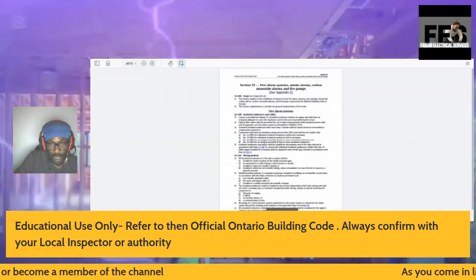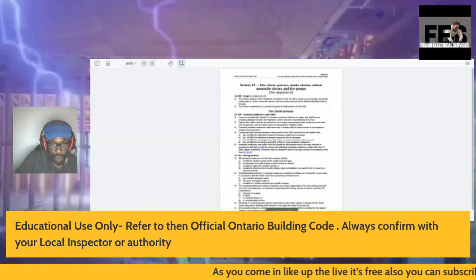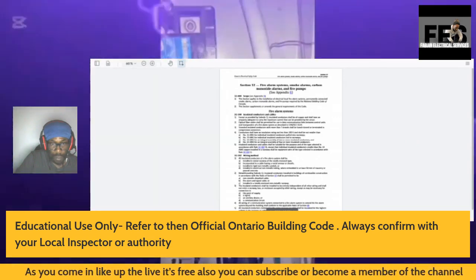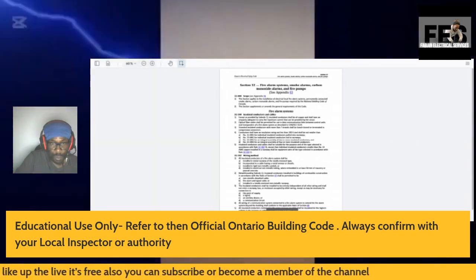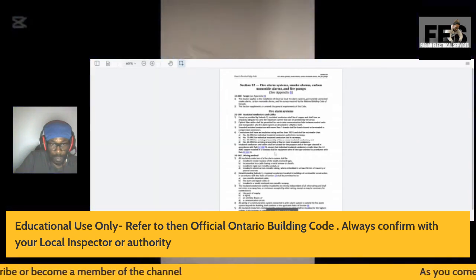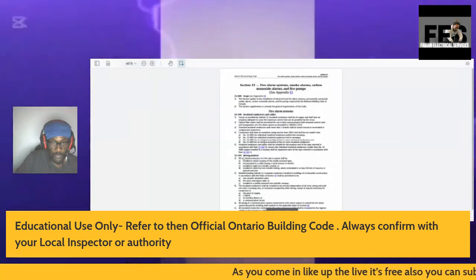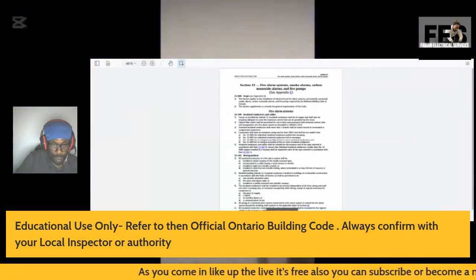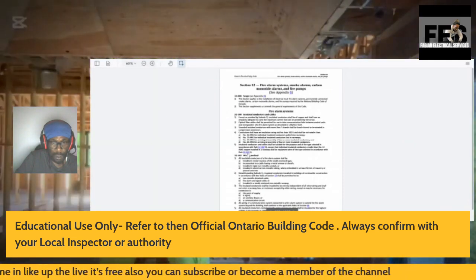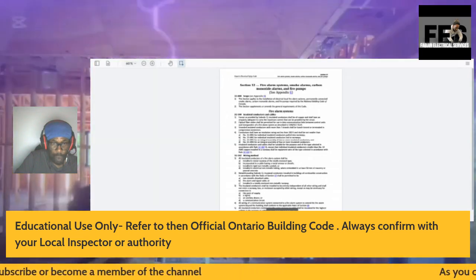Insulated conductors and cables shall be suitable in accordance with Rule 12-102, Subrule 3, except that individual insulated copper conductors shall be of the type selected in accordance with Rule 12-122. So this is basically sending you to this rule after you have read this one rule here.